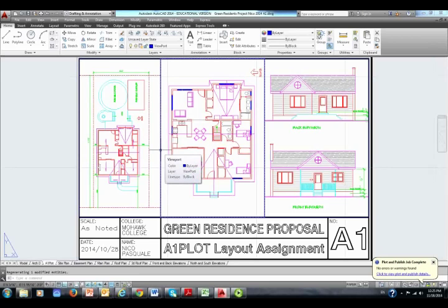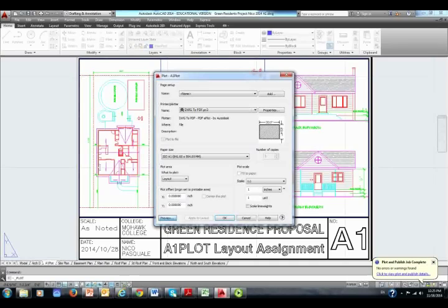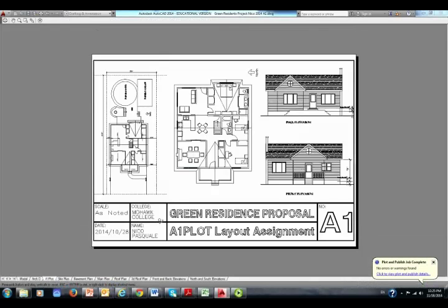They're all the same settings, and yet when I go to plot, print, preview on my A1, it comes out exactly the way I want it. And by the way, I changed A1's red color to 0.7. So there are a few settings and fine-tuning with regards to line weights and colors that I'll have to test again, and I'll get back to you.